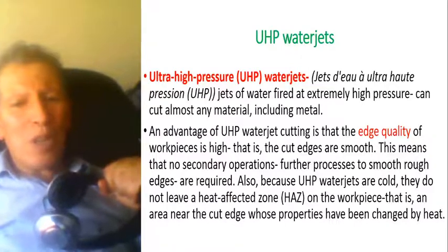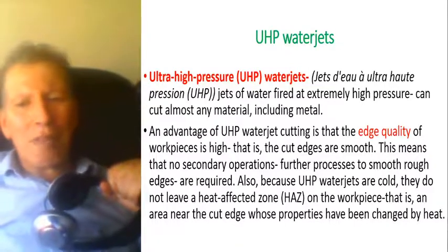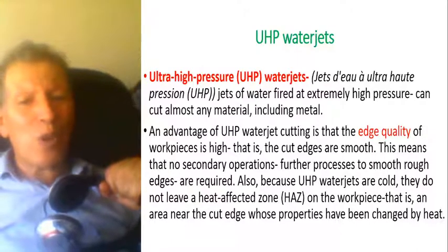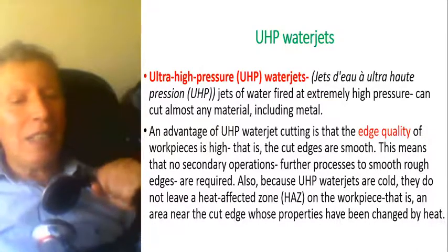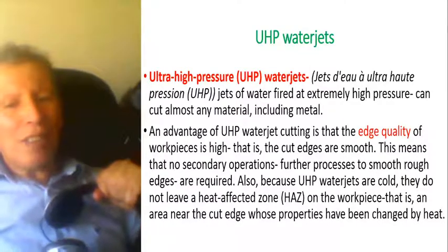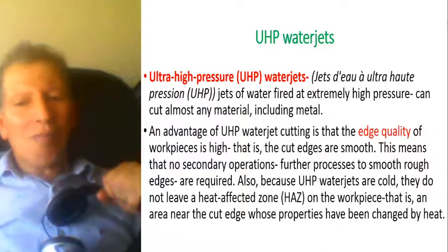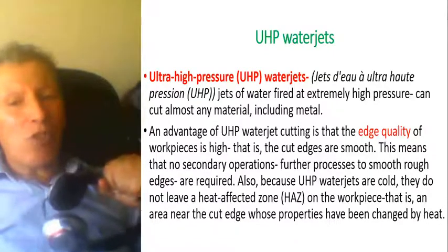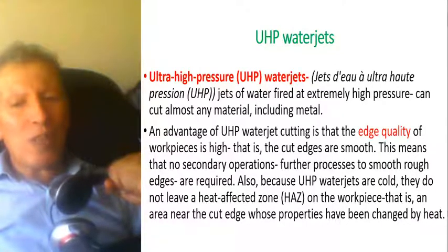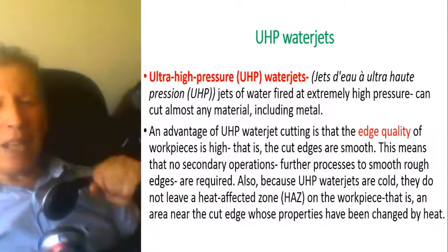So because ultra high pressure water jets are cold, they do not leave a heat affected zone. Exactly. It doesn't require heat. So it doesn't leave any traces on the workpiece, an area near the cut edge whose properties have been changed by heat.